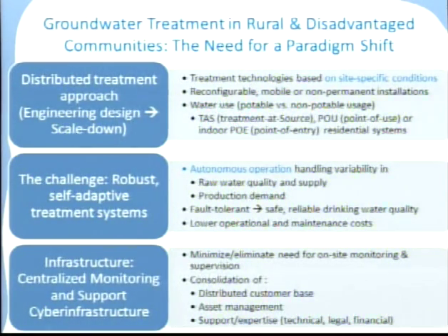In the case of RO, we heard that there is an issue that maybe there can be mineral scale. Well, we've run a system in the San Joaquin Valley up to 85, 90% recovery in the worst conditions without mineral scale. Why? Because we monitor the system with respect to composition. We have a mineral scale detector that tells us you're about to reach that condition, back off. And the system does that automatically by changing the recovery so that you're not in the danger zone. So that is what I mean by autonomous operation.